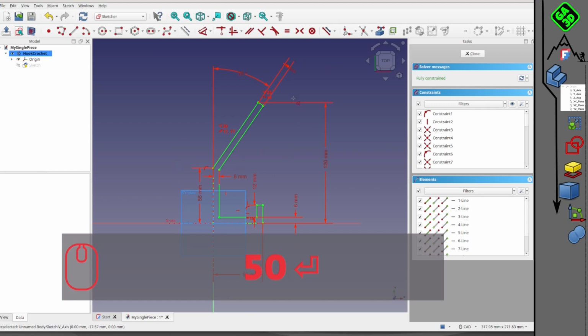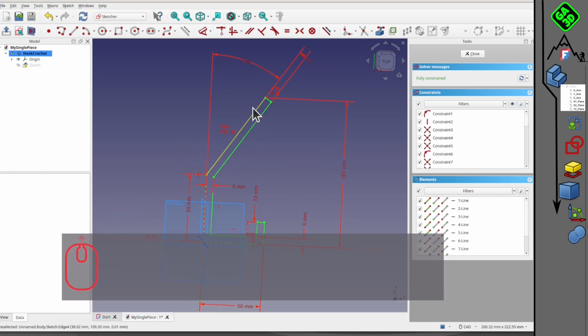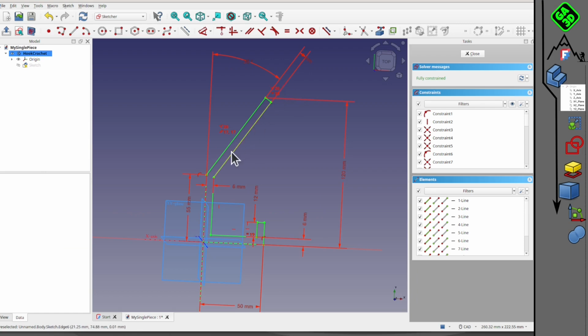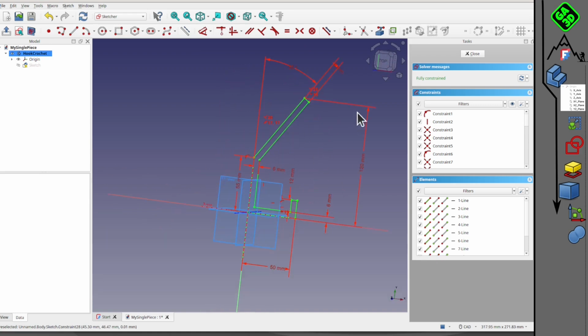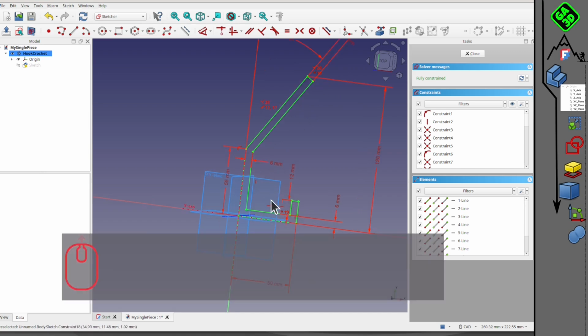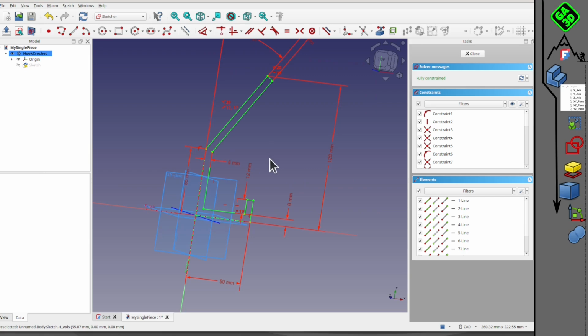We are not always obliged, in fact, to fully constrain our sketch. As we saw briefly before, I made a selection error. There was a conflict of constraints. In this case, the sketch becomes orange, and it warns you that there is a conflict. So you have to choose what constraint takes precedence over the other. But we're not going to go into those details. Just keep in mind that once everything is okay, it appears in green, or it stays white. If it stays white, you've left some more degrees of freedom, which can be quite okay in many cases.